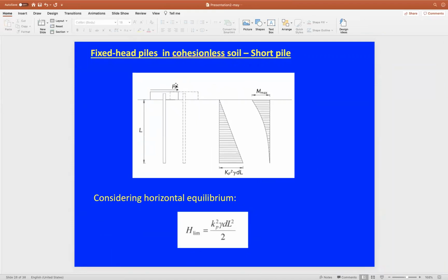We assume that the h is acting at the ground level, here by assumptions, because it's capped with the pile. To find the moments at the system at this point, we only have the resulted moments from the distributed forces here, because the moment from h, because it's passing through the point, will be 0. There is no moment arm, it's going to be 0 here.